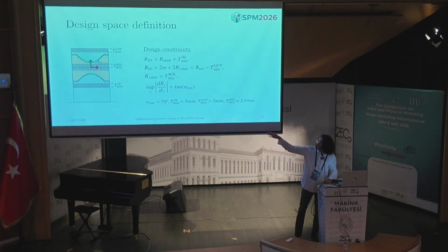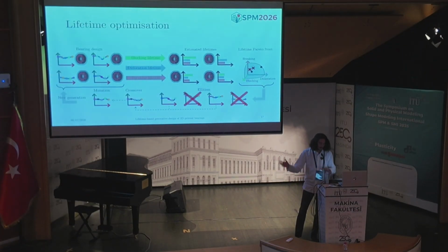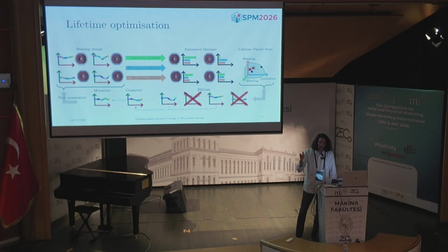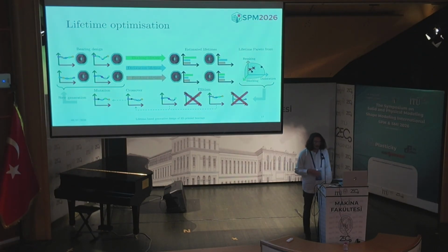So we set all the values at the bottom. And now that we have everything, we can begin to optimize the geometry. So we create a curve with a Bézier coefficient. We simulate all the lifetime coefficients we found experimentally, and then we get the minimal lifetime given the three lifetimes that we get, and we just take the lifetime, the power default with the best lifetime, and then apply a genetic algorithm in order to optimize and maximize the lifetime.